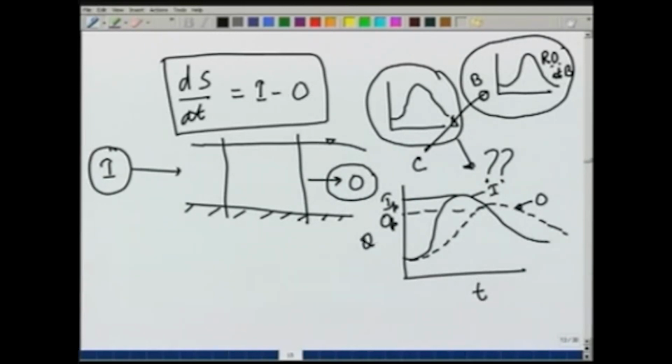If you look at this curve, the area before these two curves intersect represents that outflow is less than inflow, and therefore, water is going into storage. And what is happening is that this water level is rising, and therefore, the storage is increasing. So, water is going into the storage up to this point, and beyond this point water is being released from storage.